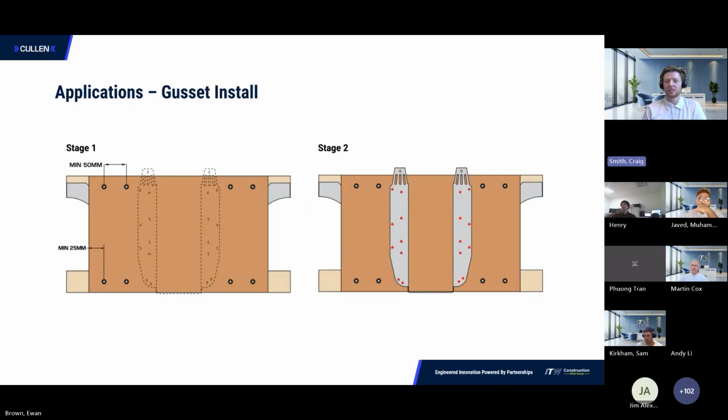I mentioned a gusset detail, so we have some details in our technical guide for this as well, and it supports the enhanced installation. It requires 8 PSTS screws. We've got 4 at the top and 4 at the bottom. And it's important to maintain a proper edge distance for a strong connection. You can see some of the minimums detailed on the screen. The plywood gusset must cover the full depth of the joist and ensure that there's clearance on either side of the hanger for the fixings as well. You can see here the hanger is quite central, and the fixings are spaced nicely either side.